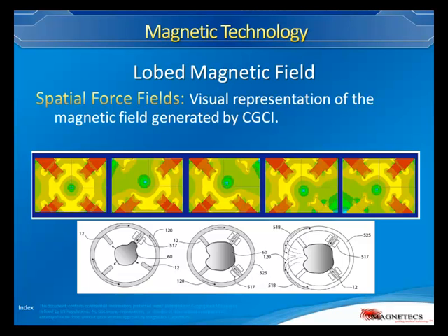So by using the two elements, we were able to produce a magneto-optical lens that directs the field based on the location of the catheter. If you have a catheter, wherever it is located, the position and orientation of the catheter is known to us. We compute the field and radiate independently 8 different coils to produce the field that allows the movement of the catheter from the actual position to the desired position based on the physician's movement.